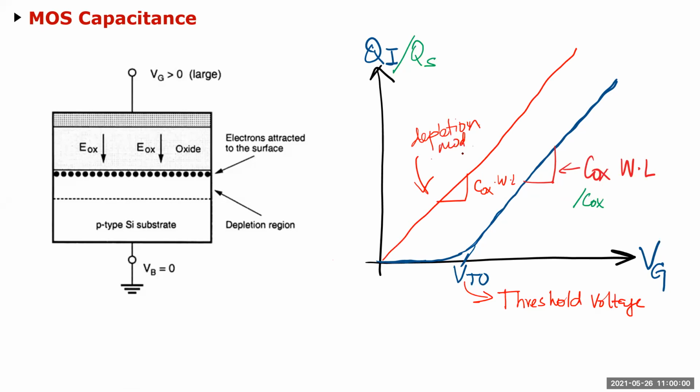It looks like a normal capacitor basically, and like I said, we use this a lot in analog IC design, because this Cox is much larger than C metal, silicon dioxide and so on. The thin oxide is about 27 nanometers, whereas in a 0.18 it is now like 4 or 5 nanometers.